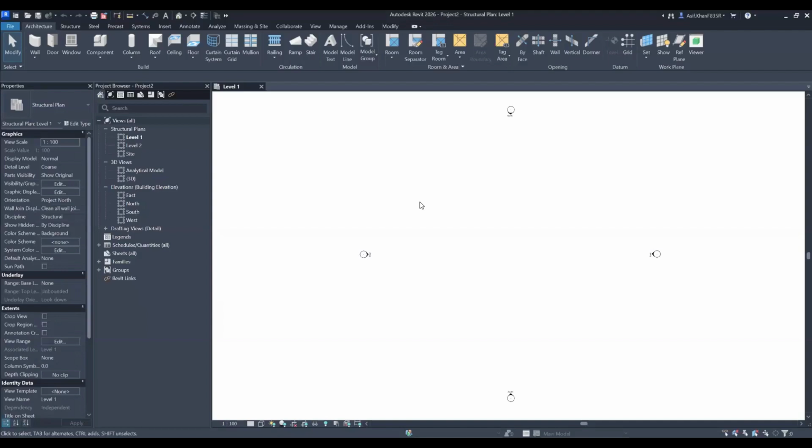All right, so let me give a bit of background about how we create those grid lines in AutoCAD. Definitely, first of all, we'll be creating layers, then a line style, then line thickness, then we'll be putting some lines for the grid. Then at the head of the grid, we'll be putting a circle, then text so that we can identify it, and assigning those to a particular layer as relevant. It's a lot of work, I guess. You also went through that.